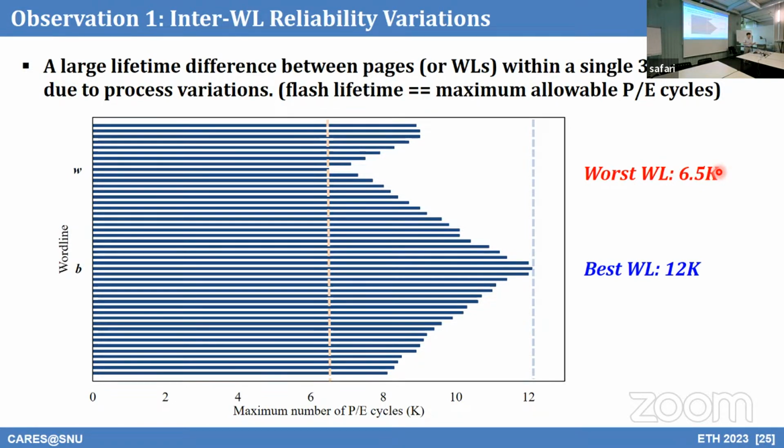So that's the end of SSD lifetime. So you may think we could use a smaller SSD for quite a long time, but the underlying assumption was that once one block becomes bad, sooner or later all the rest of the blocks will become bad and you lose data. So that's why the industry set it so that when one block of the SSD becomes dead, the SSD becomes dead. It's the end of lifetime.